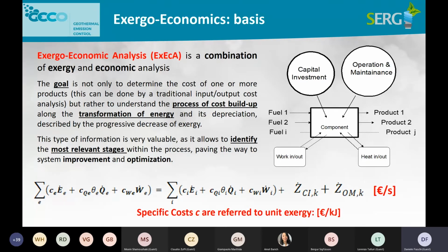Sorry, but anyhow, we have in-out Exergy flows, flow rates, heat and work, and the system delivers a useful energy product, generally heat and power. New flows introduced by Exergo-Economic analysis over Exergy analysis are the costs necessary for the system to exist, like capital investment cost and operation and maintenance (O&M) costs, in order to maintain the system in acceptably good efficiency.